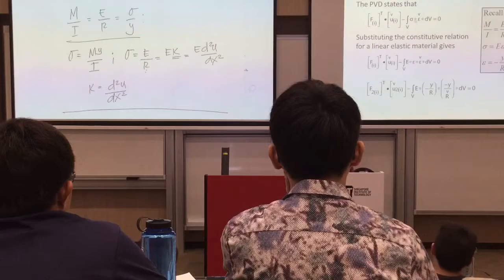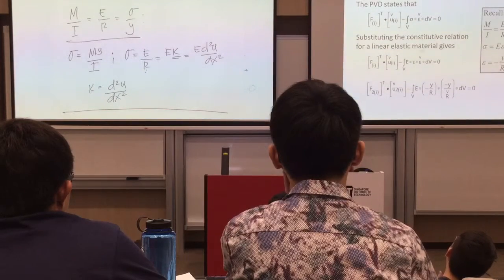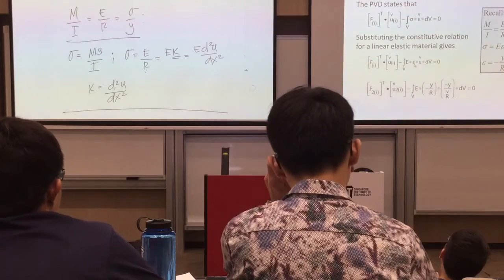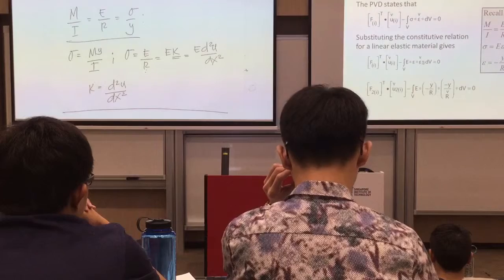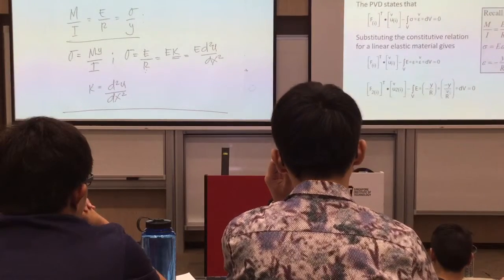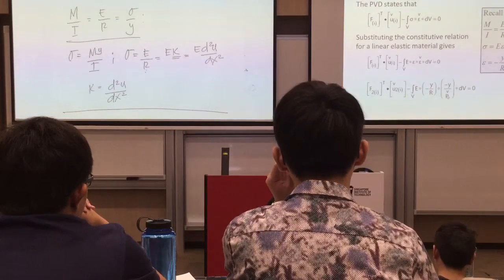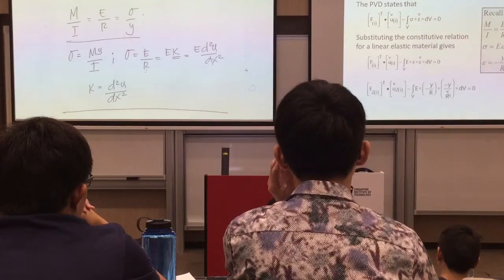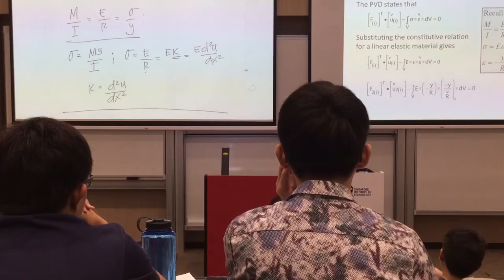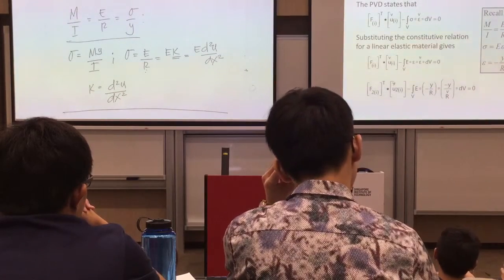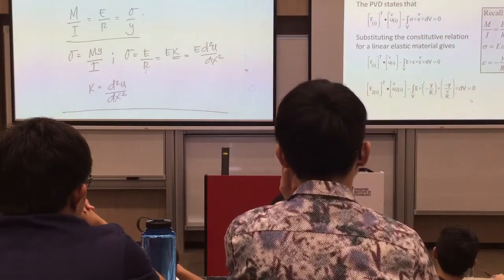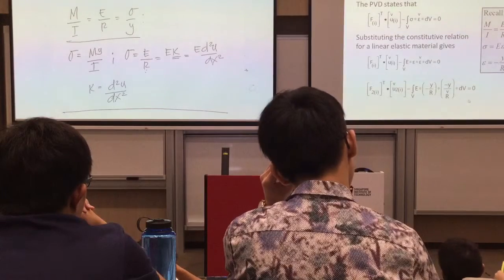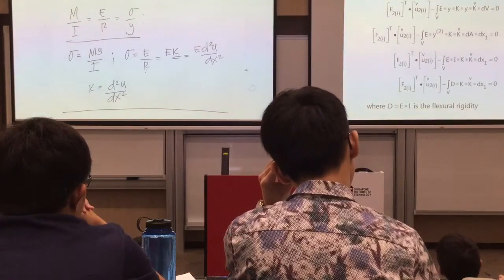So this one is that, E multiplied by strain. This strain here is equal to minus Y over R. That virtual strain is equal to minus Y all over the virtual radius of curvature. So this is the virtual value. Of course, you also have that virtual displacement somewhere here. Okay, so it's similar to what we had earlier.